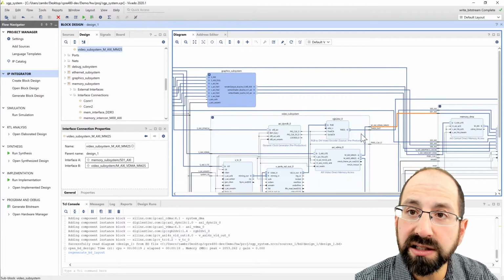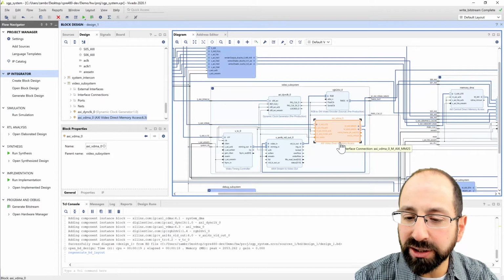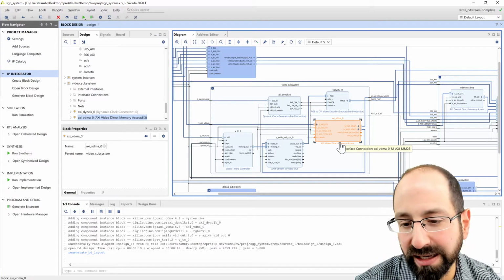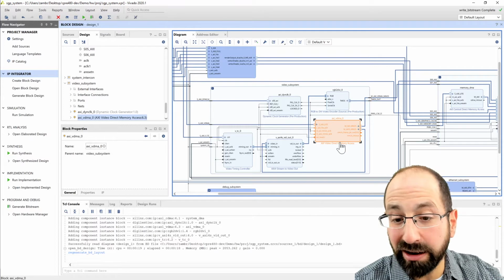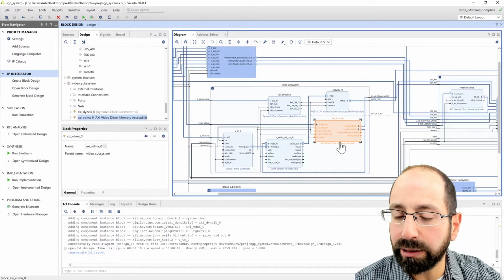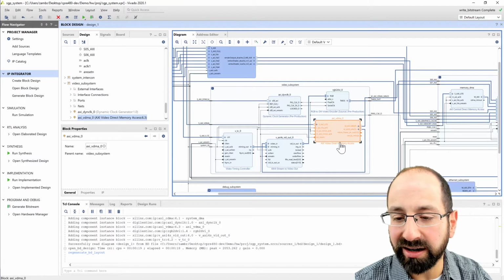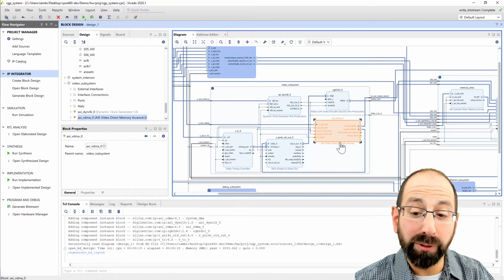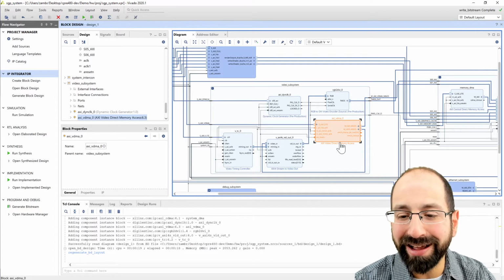In our video subsystem, we have a core whose primary responsibility, which is also a type of DMA core, is for making sure we get the next image on the screen 30 or 60 or however many times per second. And it's going to talk to all the logic for the VGA controllers to actually spit out, in this case, the right HDMI signaling to give us the right colors on our screen that we're connected to. That's one port that we're sharing amongst our multiple connections to our memory, ultimately our frame buffer here. So from an arbitration perspective, this one's pretty important, right? This one should have really high priority on that interconnect.